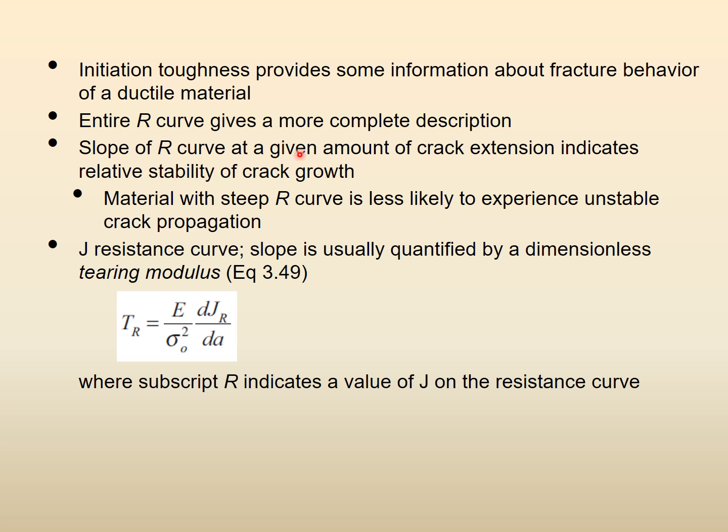If you go back to the figure, the slope is dJ/dA. A material with a steep R curve, steep, not flat, is less likely to experience unstable crack propagation.